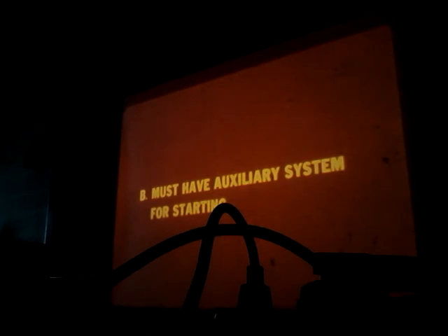Answer B is correct. The intensity of the spark from a magneto depends on the rotational speed of the magnet. And when the engine is turned slowly, as it does during starting, the magneto does not produce a hot enough spark. This requires the use of impulse couplings or vibrators.